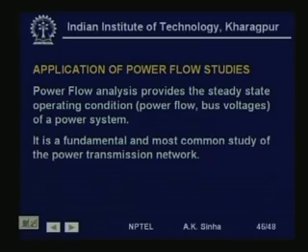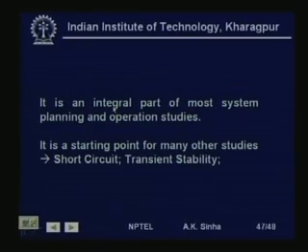Now, what are the applications of power flow analysis? Power flow analysis provides the steady state operating condition, that is, power flow and bus voltages in a power system, and it is a fundamental and most common study of a power transmission network. It is an integral part of most of the planning and operating studies that we do in power systems. It is also a starting point for many other studies such as short circuit studies, transient stability analysis and other studies.